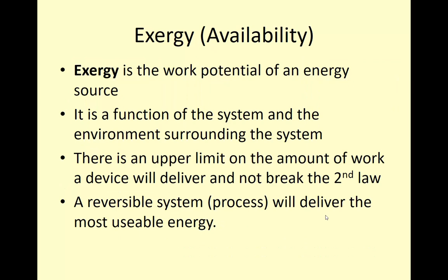So Exergy is the work potential of an energy source, and it's a function of both the system and also the environment that is surrounding the system. We'll discuss that in more detail in the coming slides. As governed by the second law, there's an upper limit on the amount of work that any device will deliver. So even if we purport to have some device that has infinite free energy, there's probably an upper limit to it that we just have not recognized.